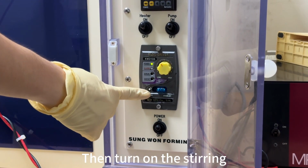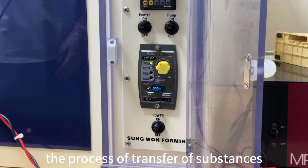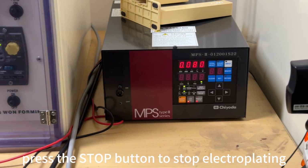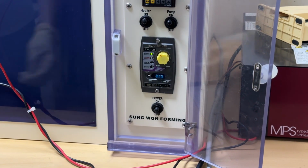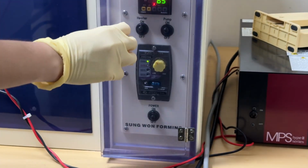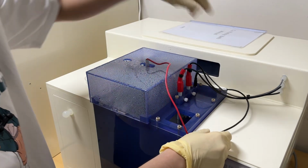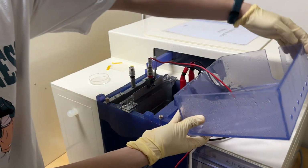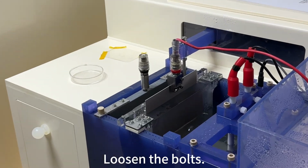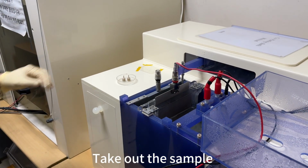Then turn on the stirring. This can improve the transfer of substances. After a predetermined time, press the Stop button to stop electroplating. Then turn off the stirring. Disconnect the wire. Open the lid. Loosen the bolts. Take out the sample.